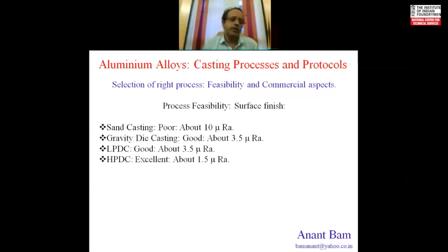The coating is a three-part system: an active ingredient, a binder and a carrier. The carrier can be water or a thinner. The binder can be sodium silicate or boron nitrate or any such sticky material. And the active ingredient can be talc, zirconia, silica, alumina, any such material.